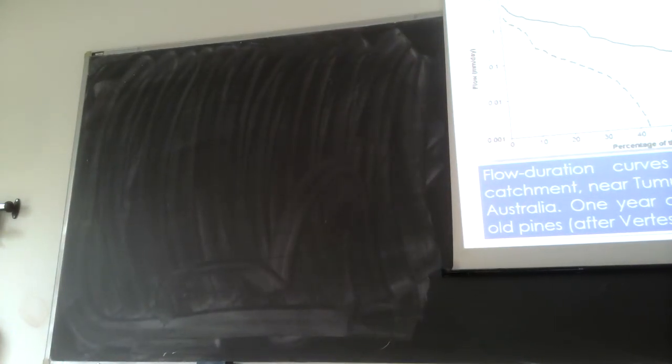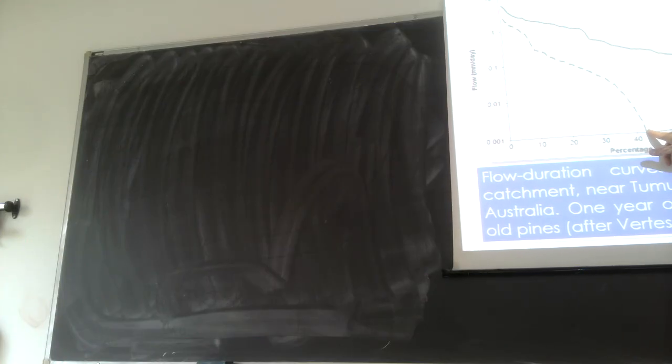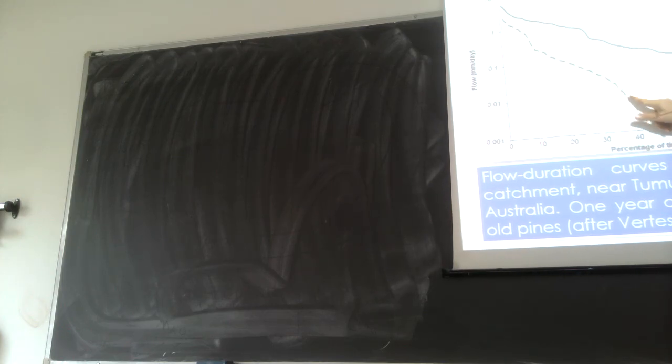So you may say, these two years are simply different. The catchment is the same, the basin is the same, but years are different because one year was wetter than the other, right? And so you have a perennial stream that for a very dry year becomes an intermittent stream. Look, this flow duration curve here tells us that in the river there's discharge for less than 50% of the time in the year, so less than 6 months. The rest, discharge is zero, okay?